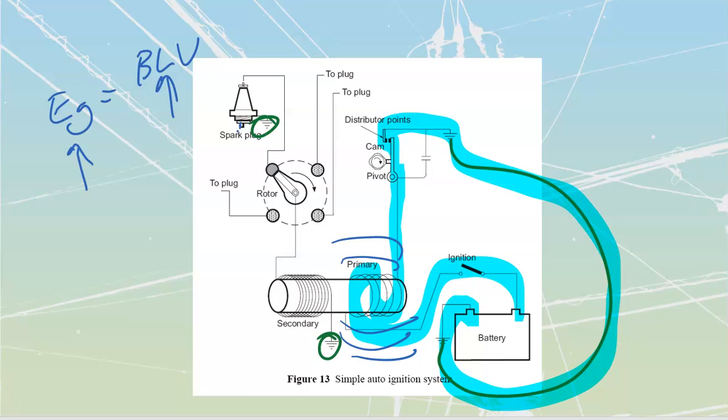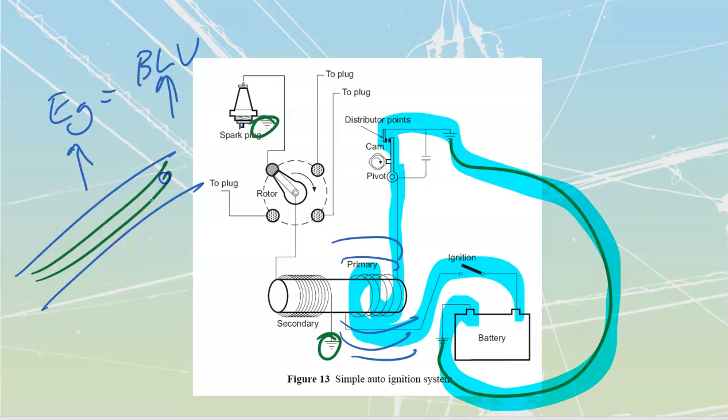Interference is a really bad thing because we just get magnetic lines that are going to be picked up from one to the other, two conductors in parallel. If I've got a lot of current passing through here, it's going to cut across this conductor over here and induce values of voltage, and all of our digital signaling is done through values of voltage. Keep them separated, okay? That's it.